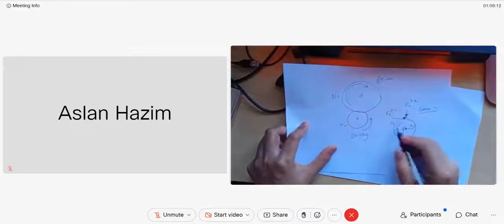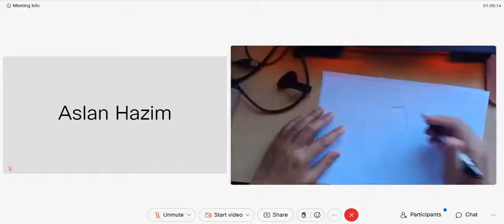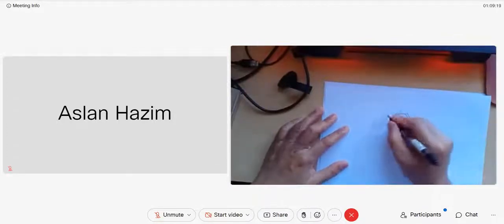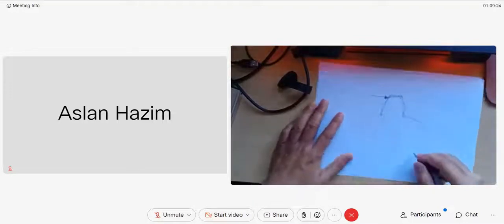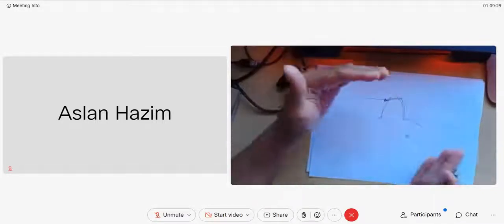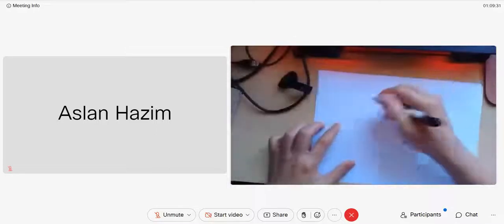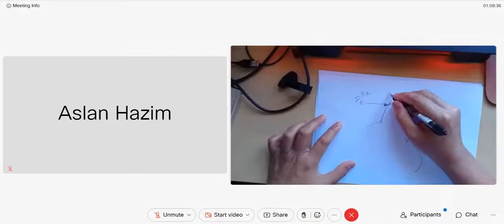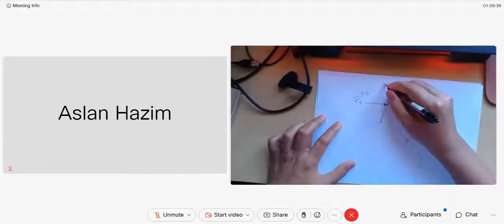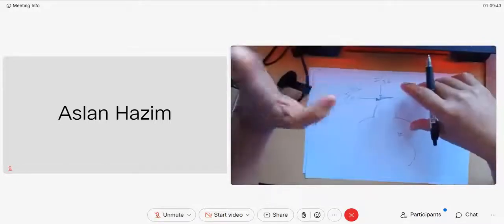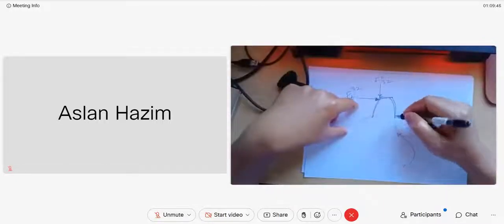If we zoom in on the tooth of gear 2, we have F tangent here acting on the surface, because gear 2 is rotating counterclockwise and it is driving. So the impact comes from gear 3: we have F tangent 3-2 and also F radius 3-2. The second part of your gear analysis is to calculate whether this tooth will sustain or not.